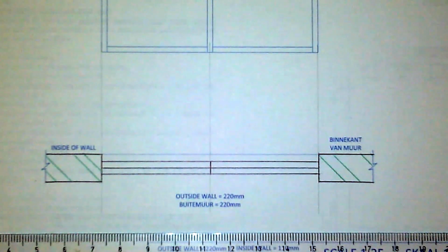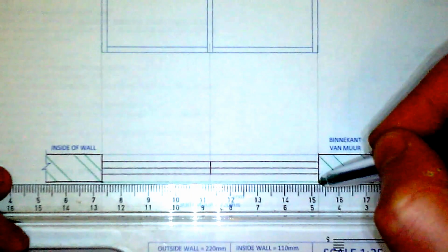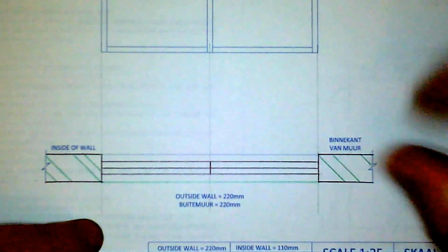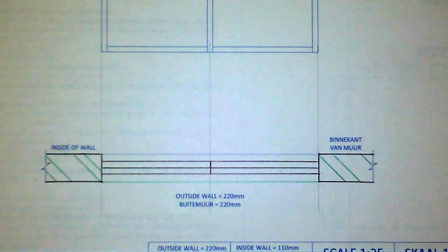Now please take note, this is again an outside door. So as in the previous exercise with swinging doors, the outside door should have a line separating inside and outside of the building. So this is the outside, but again that line should be a B line, in between dark and light. So just like with the hatching, I'm going to use green again, and all I'm going to do is draw a B line that will connect the two walls going to the outside, but you should not have this line here. Okay, and that's it guys, we are done.